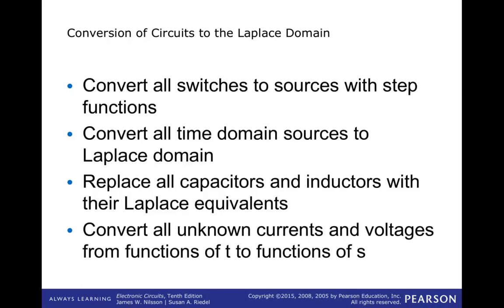The third thing you want to do is replace all capacitors and inductors with their Laplace equivalents. That includes, if there are initial conditions, you will need to include those sources shown in the previous figure to fully represent the capacitor and inductor. And then finally, all the unknown currents and voltages in the circuit are no longer functions of time, they're now functions of S. So you'll need to convert those to symbols that are functions of S. One thing to point out here is that you never mix time domain and Laplace domain. Just like you don't mix it mathematically, you don't mix it in the circuit.